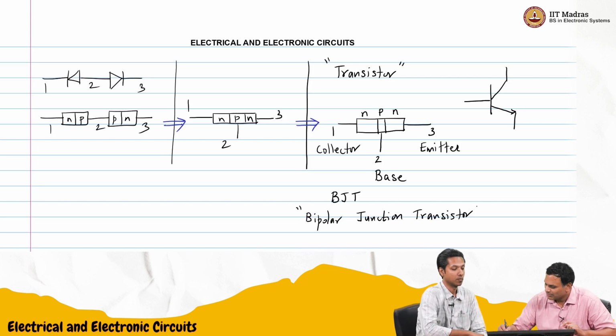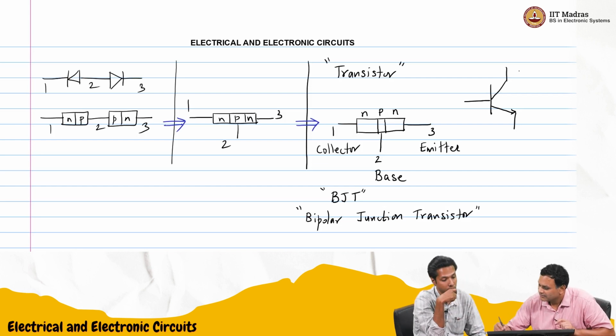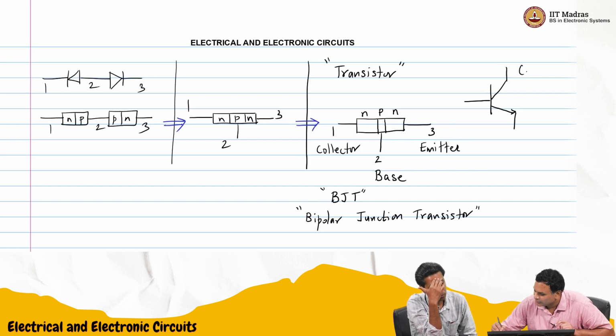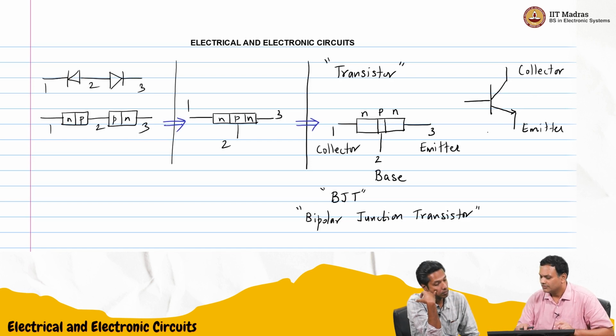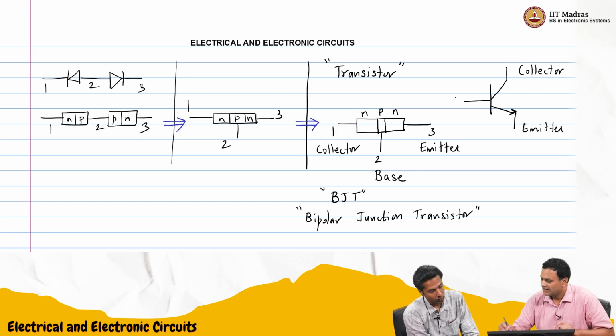This is called a bipolar junction transistor. And we have 3 terminals. So we'll mark the emitter. We chose this, we'll call this the collector. This is the emitter. The reason I drew it like this, we saw that electrons go from the emitter, so the positive current has to go out of the emitter. That's why I have shown the arrow like this. And this is the base.